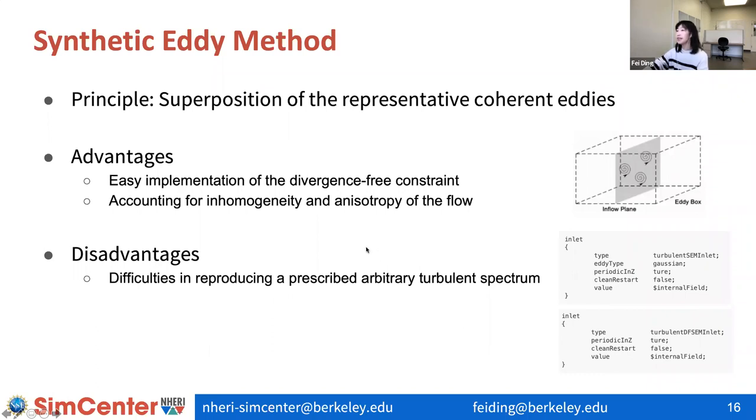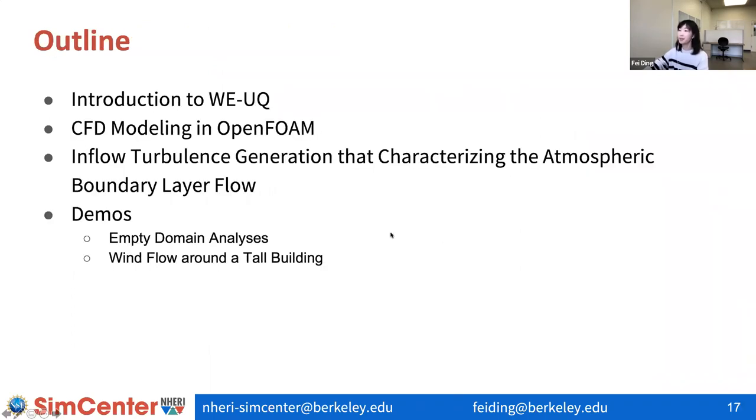And to use this synthetic eddy method, you can call the turbulentSEMInlet, or if you want to use a divergence-free synthetic eddy method, you can call the turbulentDFSEMInlet in your OpenFOAM initial boundary conditions in order to use TInF for inflow turbulence generation on the inlet surface.